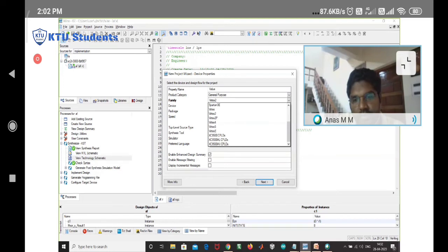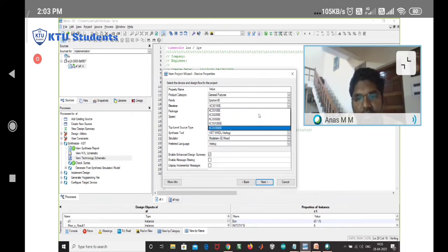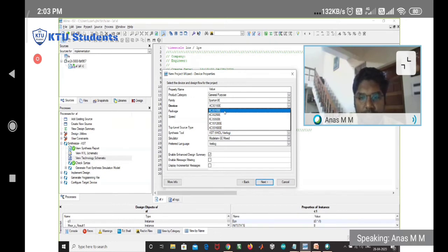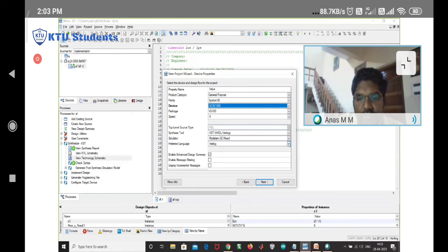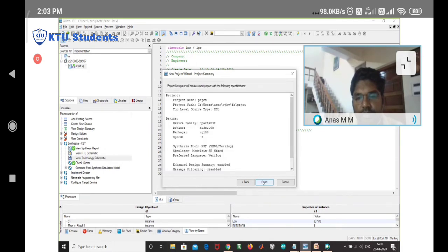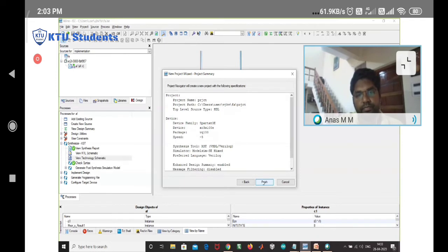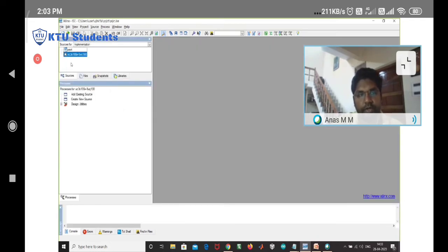This is an old simulator. Now the industry is using Vivado simulator. I don't have that software, so that's why I am showing in this ISE simulator. I am selecting a hardware called Spartan 3. This is a logic family or FPGA family from Xilinx. And here we can select the devices. Under Spartan 3 family, you have different types of devices, depending on the hardware complexity. You can select any hardware, depending on your project or your requirement. Another important factor you need to select is the language. So as I mentioned earlier, we have two hardware description languages. One is Verilog, another is VHDL. You can select anything. Okay. So now I created a project for a specific programmable logic device.